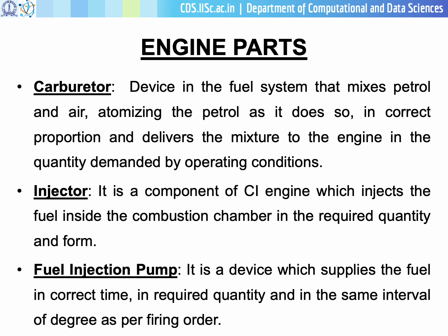Injector. It is a component of a CI engine which injects the fuel inside the combustion chamber in the required quantity and form. The FIP, or fuel injection pump, is a device which supplies the fuel at the correct time, in the required quantity, and at the same interval of degrees as per the firing order.